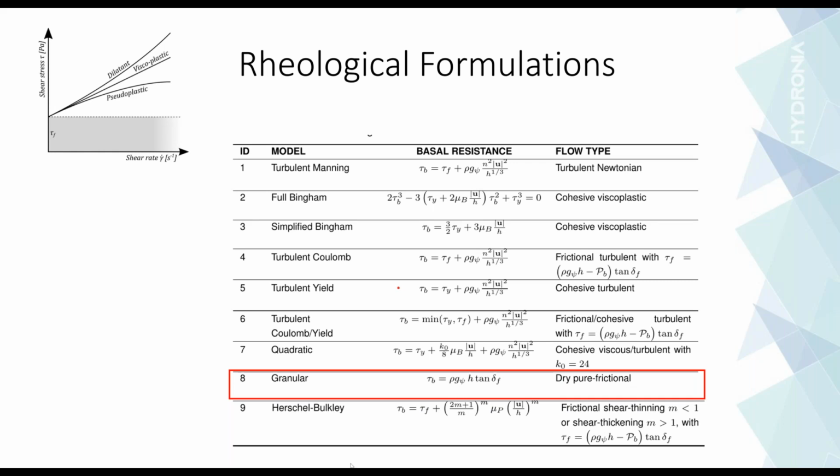We also have added recently the Herschel-Bulkley model, which is quite popular in some applications where you have high concentrations of viscous or fine material that create a very viscous flow. So you have all these options, and particularly the granular will be the one for the dry stack.